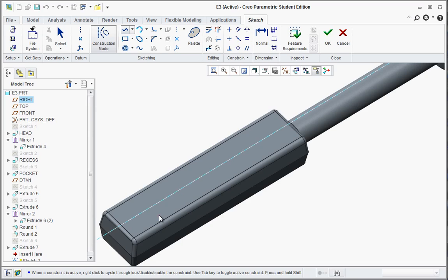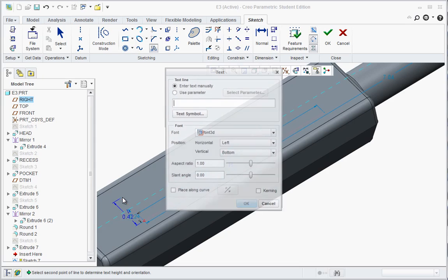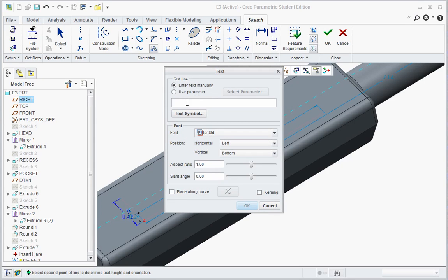Like you're drawing the baseline for the text. So I want it to start right about there to right about here. Okay. Now with that selected, turn off construction mode. Click on it again to turn it off. Go to the A, that's right there, that's for text, and glide up to this point that you drew. Click and drag up the vertical length or height of the letters that you want for the text. So I'm just going to eyeball it right here. Click. You could type in a value, but in this case, start typing in what you'd like to put on.